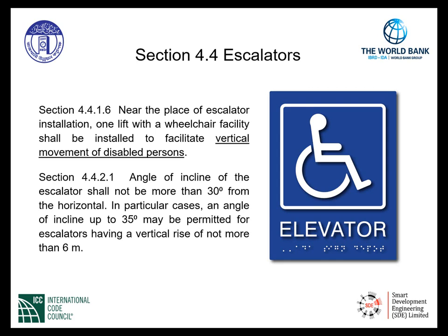Section 4.4.2.1, the angle of incline of the escalator shall not be more than 30 degrees from the horizontal. In particular cases, an angle of incline up to 35 may be permitted for escalators having a vertical rise of not more than 6 meters.